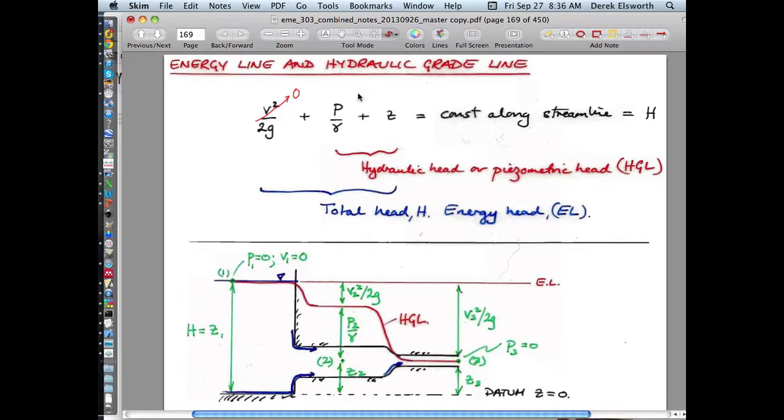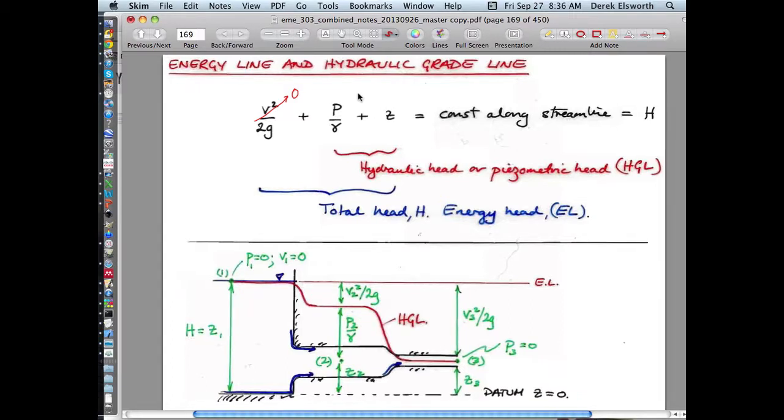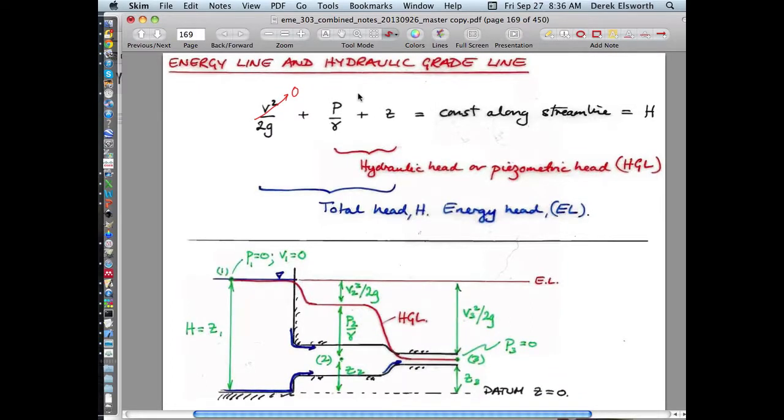And the other significant thing that you deal with when you're dealing with fluids in porous media is they're not inviscid. They actually have fluid losses as you go from where you're pumping something in to where you're pumping something out or recovering something. And that is taken care of in the permeability, which is the mechanism by which we accommodate changes, the loss of energy in the system as you go between upstream and downstream.